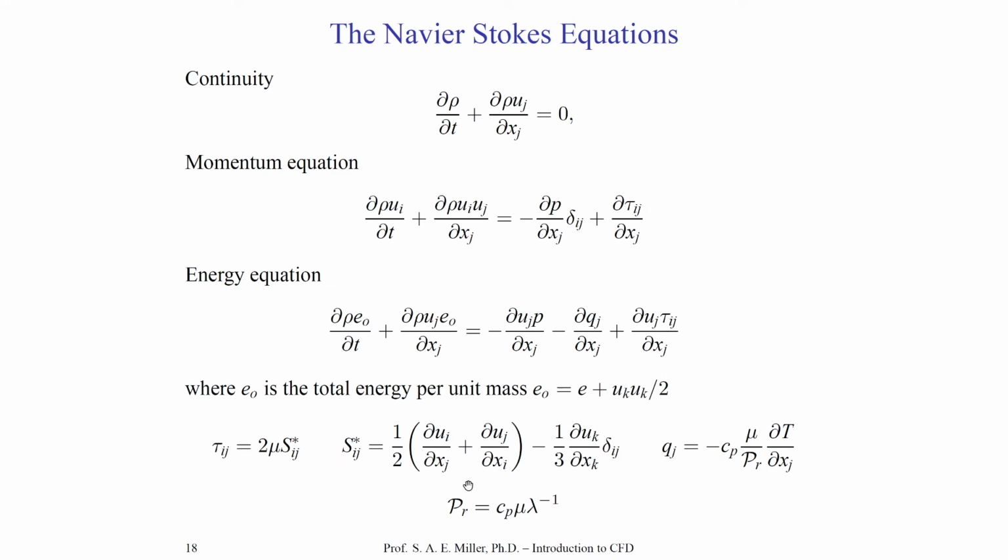These other terms are placed in the equations. Pr will be the Prandtl number, which is a non-dimensional quantity. Tau ij is, of course, the shear stress term. And in this form, you'll see I don't have a second coefficient of viscosity. I've used Stokes' hypothesis. This is probably the most common form of the differential equations of motion, the Navier-Stokes equations with an energy equation that are compressible and unsteady that are used in CFD. We would typically go to these equations to create turbulence models themselves, which would be evaluated by CFD later in the class.